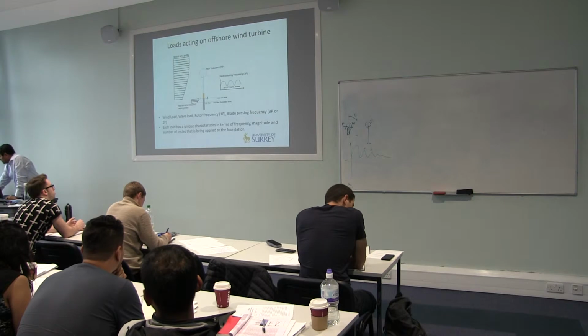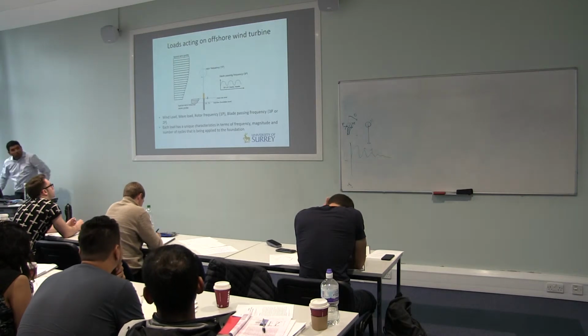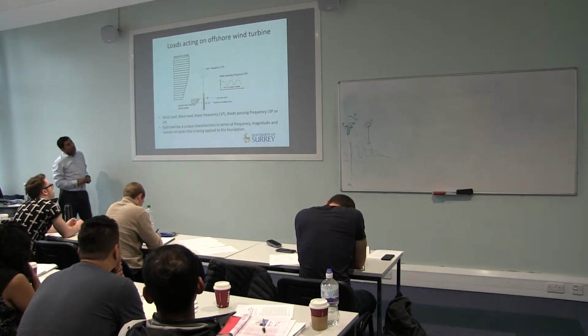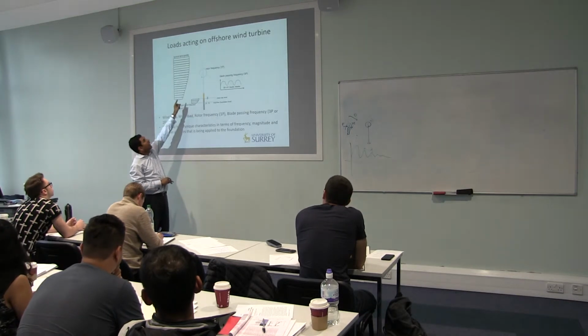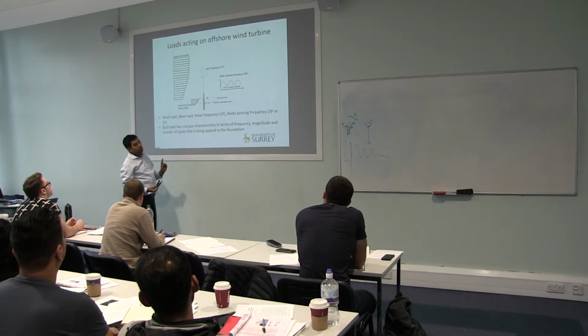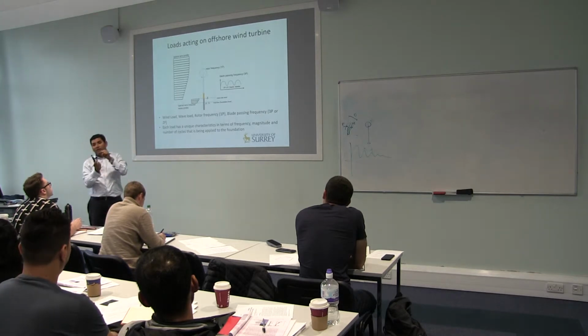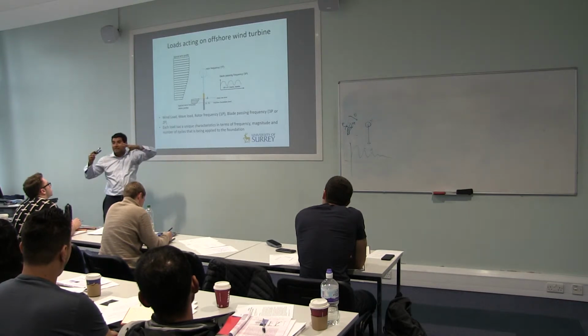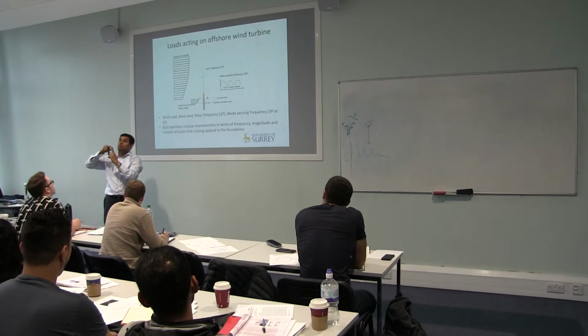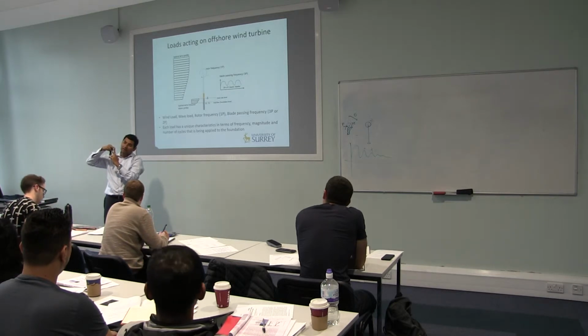In terms of loads, the loads on the whole thing are wind load. Wind load will act, and the main thing to find is the load at the top of the tower, so the thrust on the top of the tower. Because the whole wind will be captured by the blades. The blades will give a point load at the top of the tower.